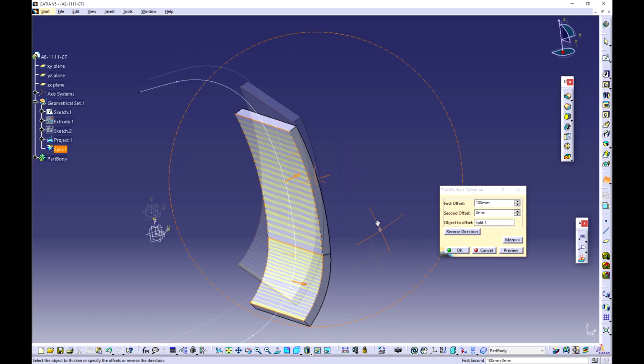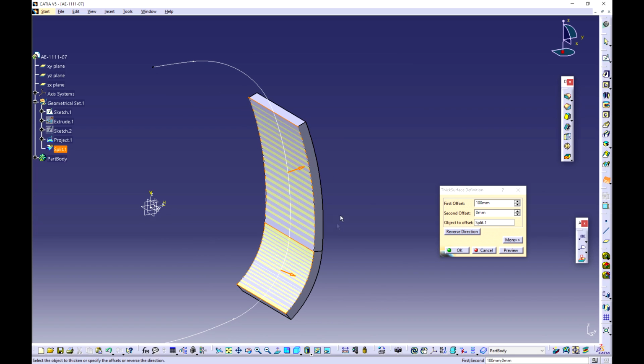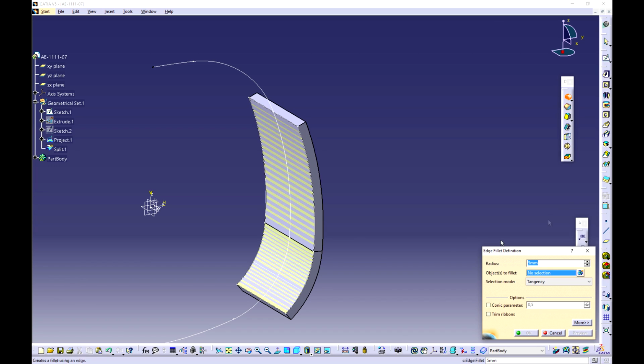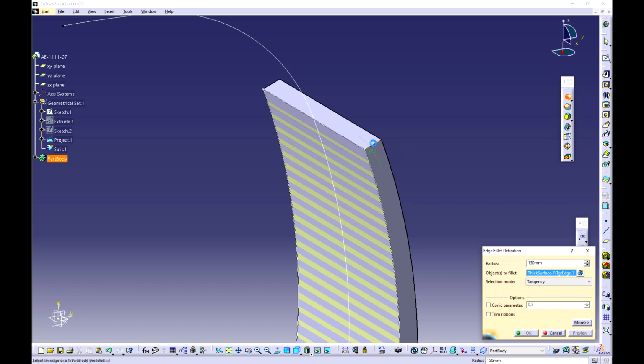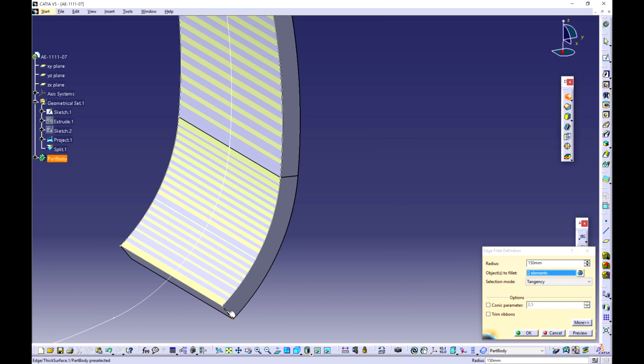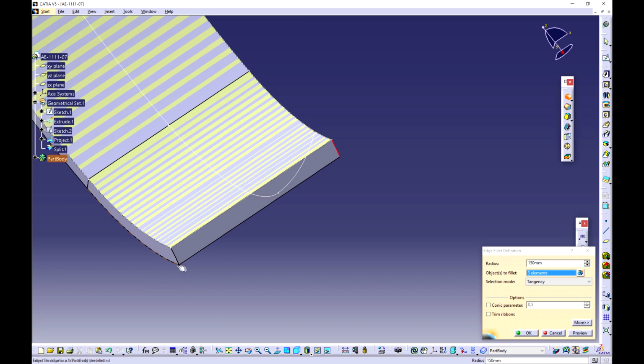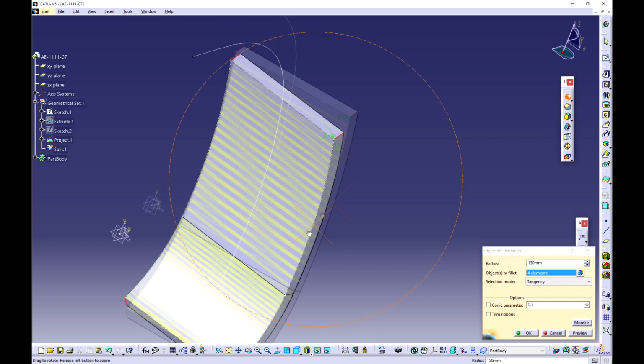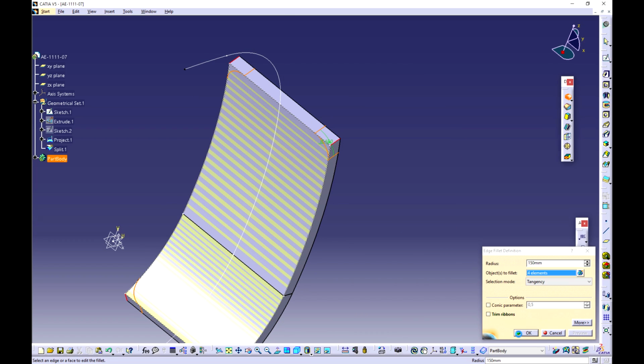Then it's very thick. We are changing this because our surface shouldn't be that thick. It would be pretty heavy, too heavy for an airplane door. But first we check it. It's okay. Now we are making edge fillets. Click on edge fillets and type in a value of 150 millimeters, and objects to fillet are our corners. So this corner, this, and this corner. Should be 4 corners in total, 4 elements. And preview, beautiful, looks good.